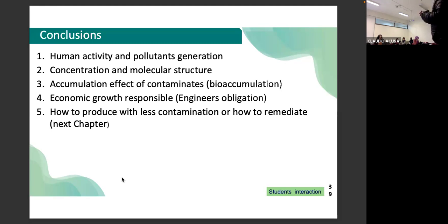The only restrictions are to have cost-effective equipment. One of the problems is dealing with solid-liquid, fine particles, with the residual solution. Sulfate is a big problem, even for mining companies. Removing sulfate is a pain. Big one. We haven't solved that. Anglo American today is accumulating a lot of gypsum, which is very unstable because they have neutralization of acid solutions, and they're producing a huge deposit of gypsum. So sulfate is something that we don't really have clear how to remove.